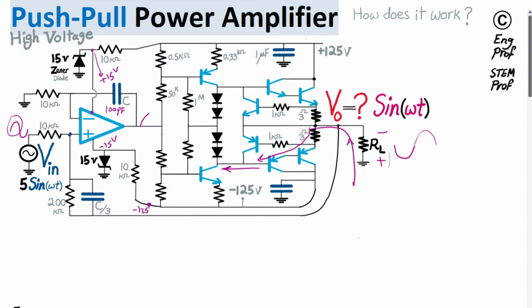This is an indication of proper wiring in this circuit, because the input, in the positive cycle, is trying to increase the voltage at the positive terminal. So it tries to jack up the voltage here. At the same time, the output tries to decrease because we are in the negative cycle, counteracting what the input is trying to do. So this is a negative feedback wiring, which is exactly what is needed. So negative feedback in this circuit.